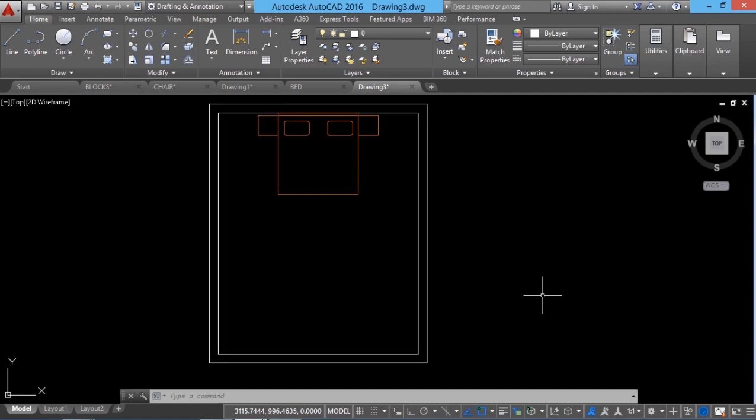In the third method, we create a drawing right from the scratch just as we have done for the bed. Then using the base command, you re-specify the insertion point from origin to a convenient location. Then you save that file. Such a drawing file can be inserted in any other drawing using the browse option of insert command. This is exactly what is preferred.